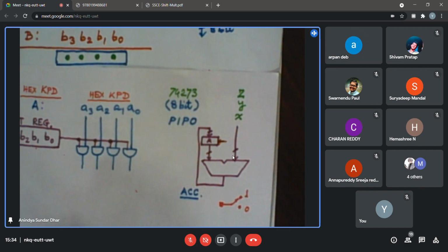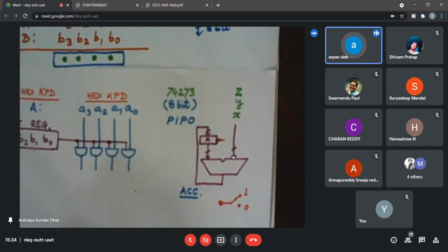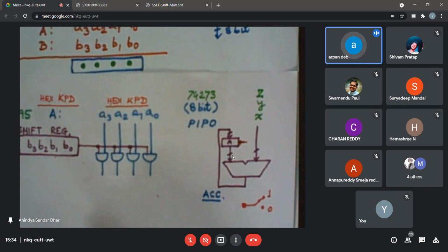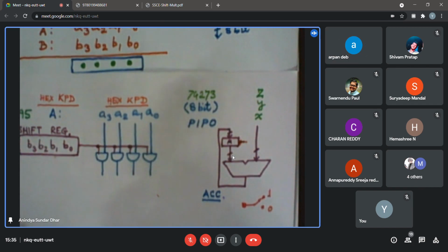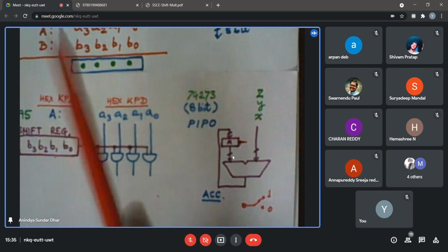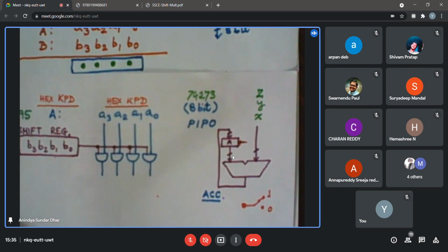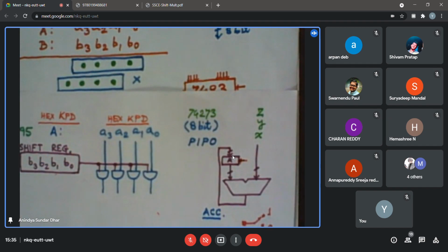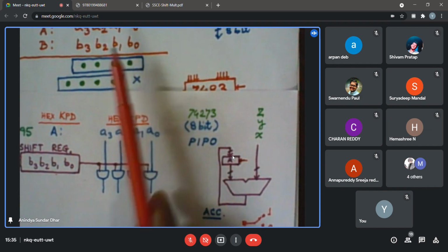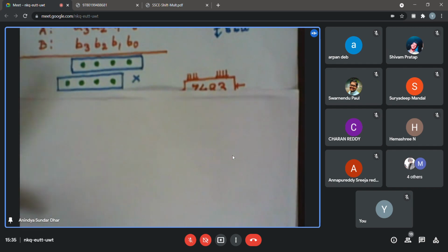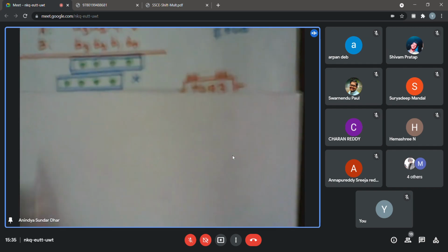Sir, if we directly connect the outputs of the AND gates to the adder, the partial products have to be shifted before adding, right? So how will that be accomplished? Think about whether I really need to connect all the 4 bits to the adder, or something else. The first operation is trivial. Initially it is 0, adding with 0 is nothing. So if you think about just adding the first 2 partial products, maybe I can cover this one. I'm talking only about this portion.